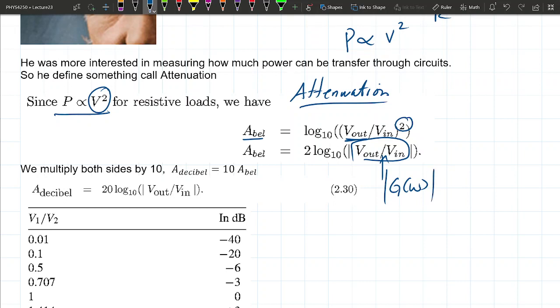And we're going to take an absolute value of it because there could be stuff that has negative gain, and then what will end up happening is that you try to take a log of a negative number, you punch it in your calculator, and you're going to blow up the calculator, right? Okay? You can't take a log of a negative number, so we just need the absolute value. Okay, and the decibel, now we turn pink again.